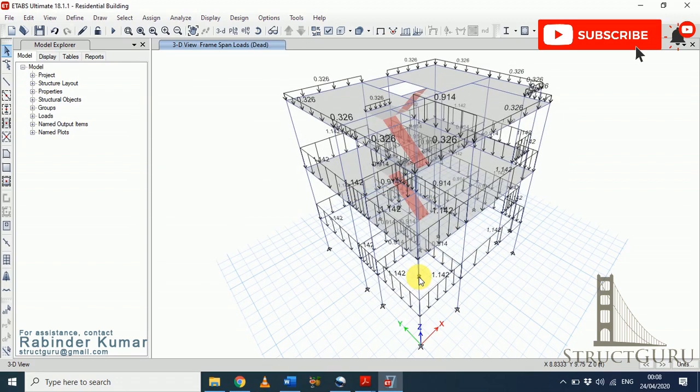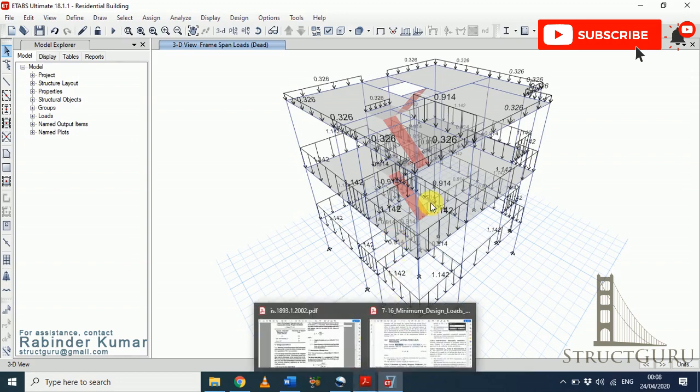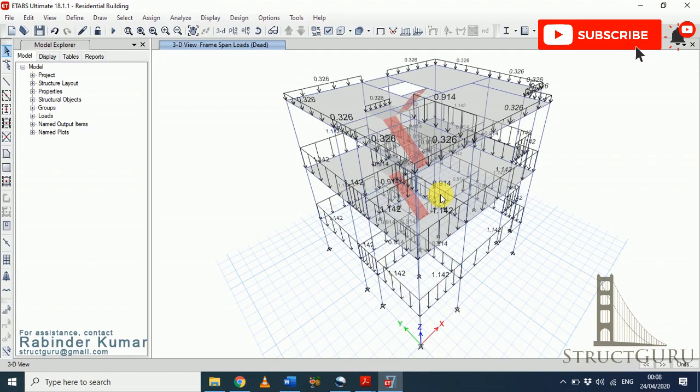Now let's discuss the mass source. This is very essential for considering lateral load and seismic design of buildings. This means how much seismic weight we should include for calculating the base shear. So let's see what the provisions are in the ASCE 7-16 manual and the IS Indian Standards building manual. Somehow the values are the same in all the codes which you follow, but let's compare.